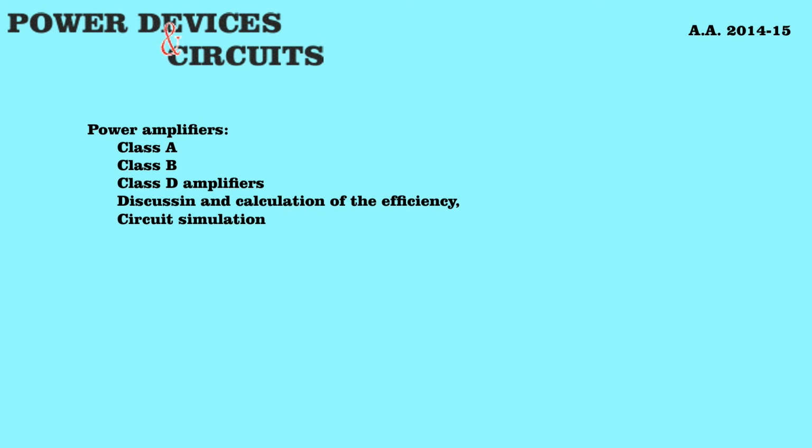This is the input signal, a sinusoidal one. This is the generator of the triangular waveform. This is the comparator. It's not a very simple comparator because there are some tricks in this circuit that are not obvious at first glance. And these are two N MOSFETs that will drive the output to the maximum or to the minimum.